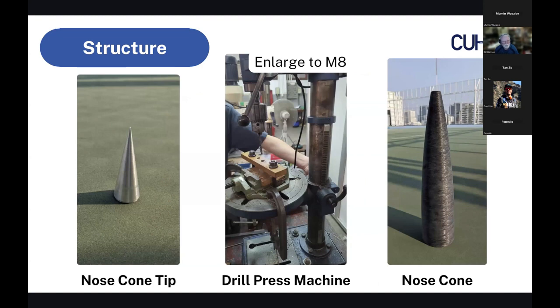The shape of our nose cone is one comment, and we have to enlarge the nose cone tip because last year the thread inside was completely stripped, so we increased the diameter from M6 to M8 to increase strength.